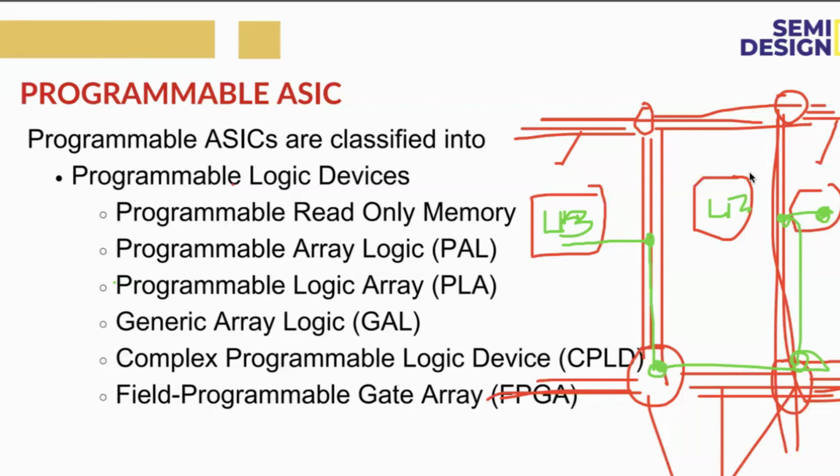Can anyone explain what I have explained with this diagram? In the logic blocks, we can have some predefined data based on the programming we have done on the FPGA, and memories, what we call a lookup table, which is basically a combination of AND or NOT gates, and we have some definite inputs and outputs of this data based on the programming we have done in the FPGA. So this is how the processing takes place.